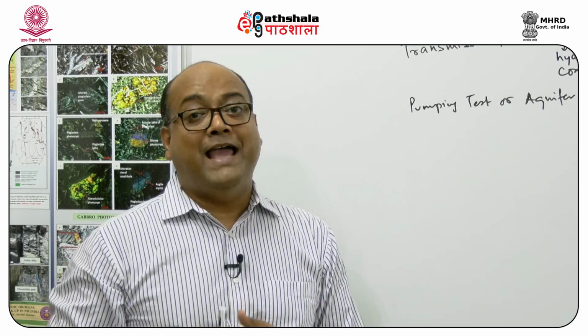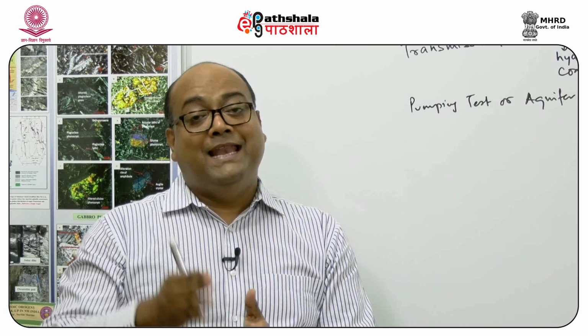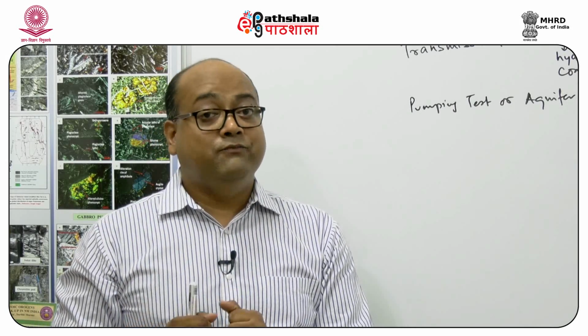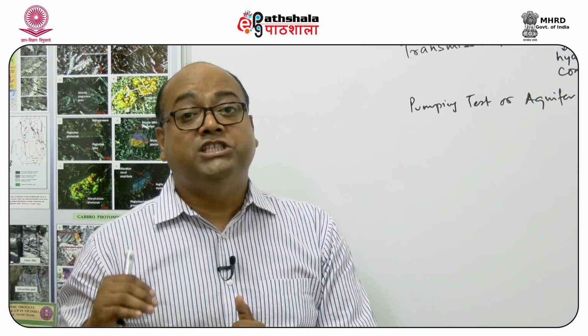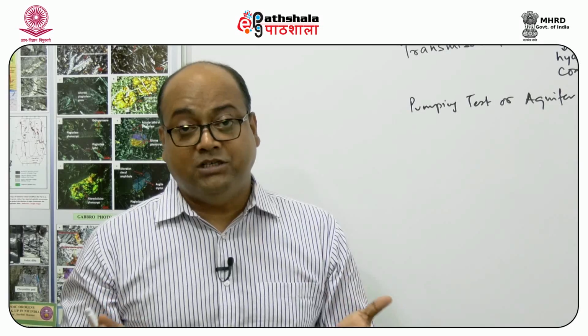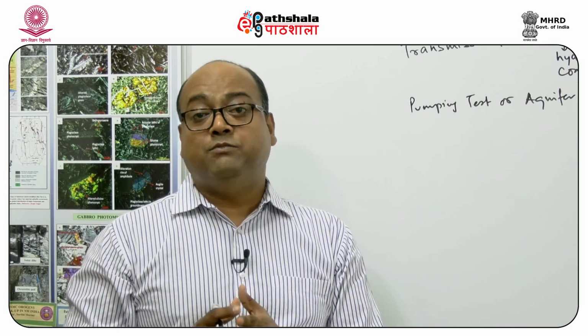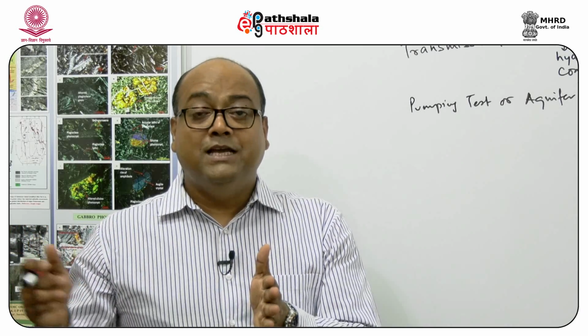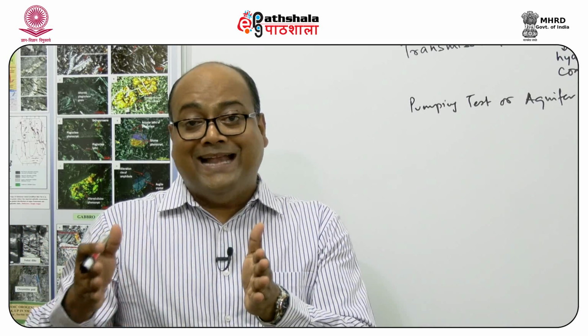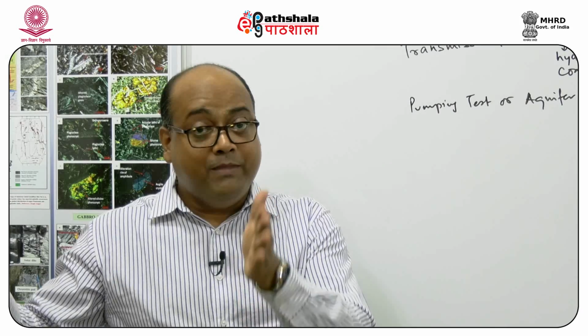So for example, if I have one pumping well and another observation well, in this observation well, how much the drawdown is changing with time is measured. And in some cases we have one pumping well and several observation wells, located at finite distances from the pumping well.